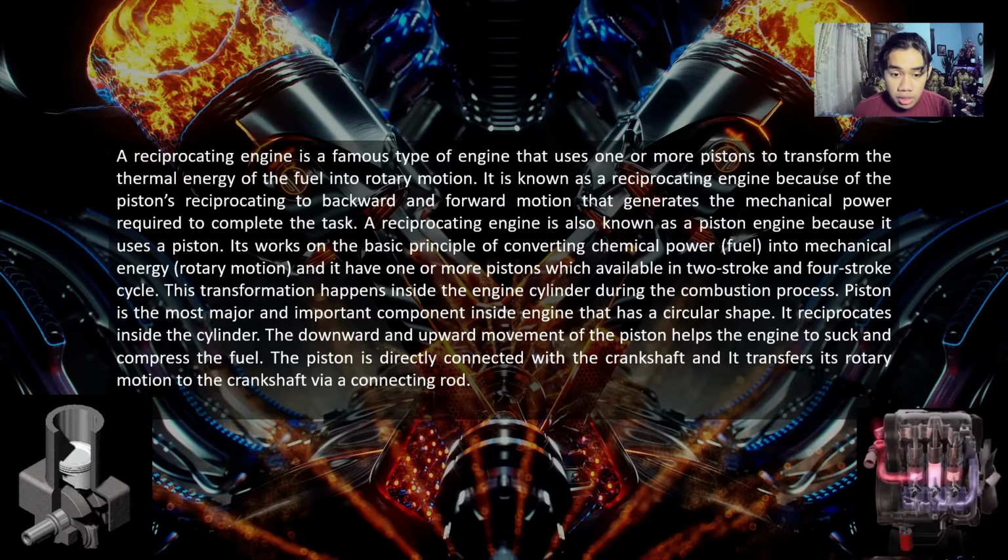It works on the basic principle of converting chemical power, that is fuel, into mechanical energy, the rotary motion, and it has one or more pistons, available in 2-stroke and 4-stroke cycles. The cycle is first intake, the second one is compression, the third one is power, the combustion, and the last cycle is exhaust. This transformation happens inside the engine cylinder during the combustion process.